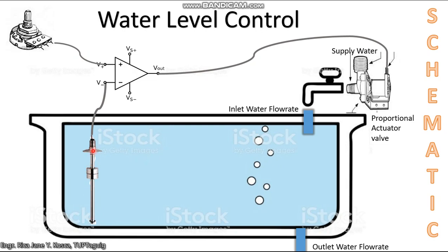Okay. So if, for example, literally in this drawing, the height is only this much, as compared to the height of the bathtub, it means that the maximum height of the water will be only at this point. So it's very important to know the specification of your float switch and the specification or dimensions of your bathtub.